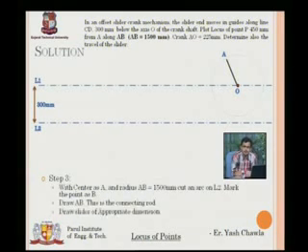What will be my next step? With center as A, as we did in the previous question. I have my position of A. Now for that I need the position of the slider. For that I need to know where the initial and final points of the connecting rod will be, because A will be the initial point of the connecting rod. The final point of the connecting rod will be connected to the center of the slider. So if I have the length of the connecting rod from A to the path of the slider, I will have the slider position.